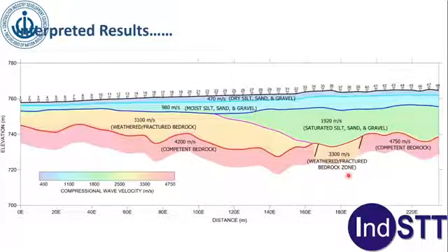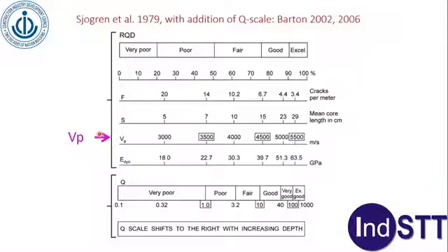Of course, for people who are more conversant with the geotechnical terminology, there is a Barton scale which correlates Vp with your traditional Q scale or RQD. And so applications are bedrock profile, rock quality and depth, thickness of overburden, fracture and weak zones, topography of groundwater, rippability assessment in mines, slope stability studies, pipeline route studies. A wonderful technique to find out the hardness of the strata.